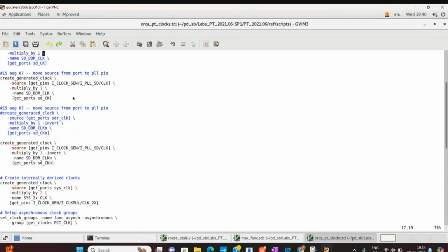Remember the asynchronous counter: there is a D flop, the Q bar is connected to the D input, and you take the output from Q. That Q is connected to the clock pin of the next flop.